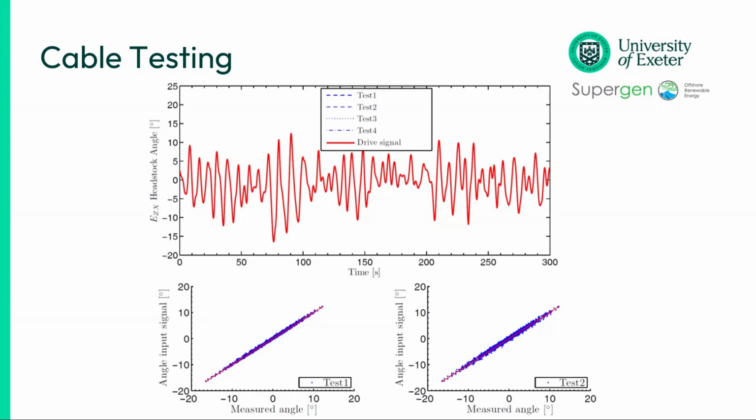You can see it's following the angle very nicely, and if you look at the time series here, you can see some of the speeds as well, and some of the wave groups from that numerical simulation. So we have to set up some of those controls every time we run the rig. It's very much tailor-made to whatever the component sample is, because it's also a coupled system with both axes. However the cable responds will affect how the rig operates.